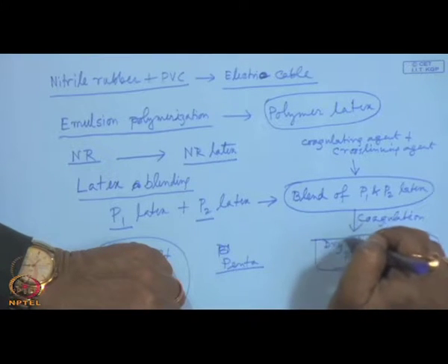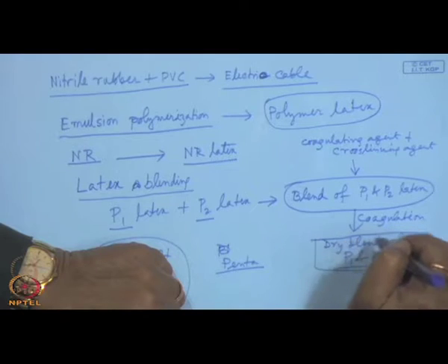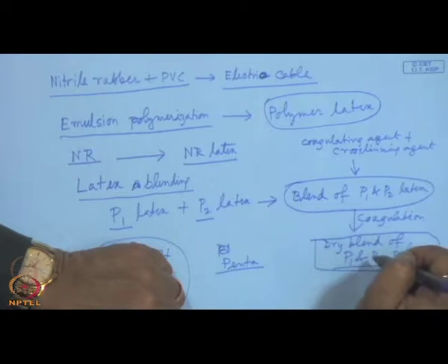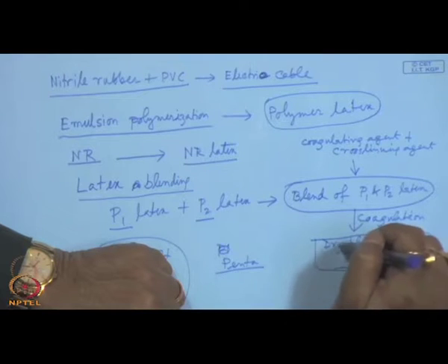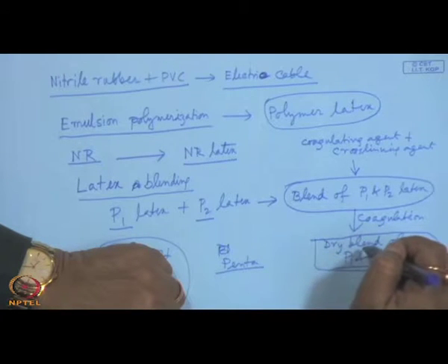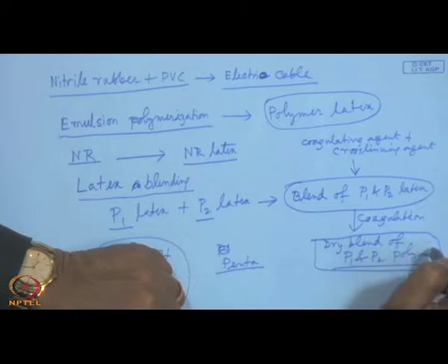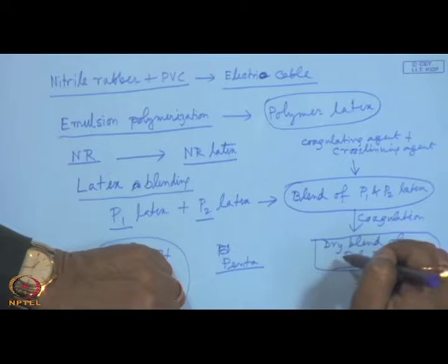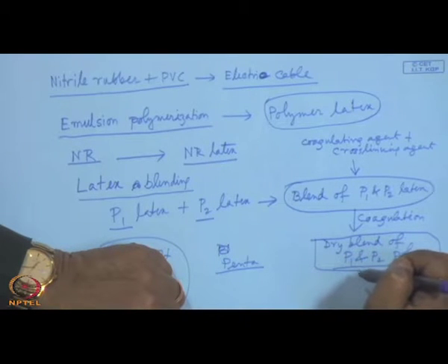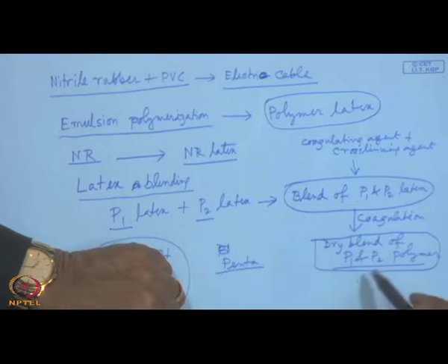After coagulation of the 2 component polymers along with this cross-linking agent, it is washed and purified, then it is given a shape and heated in an oven or in a mold, where during heating the cross-linking agent present in this coagulated polymer blend will decompose to form some active ingredients which will form a 3-dimensional network of the polymer chain.